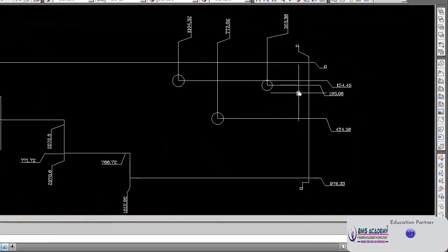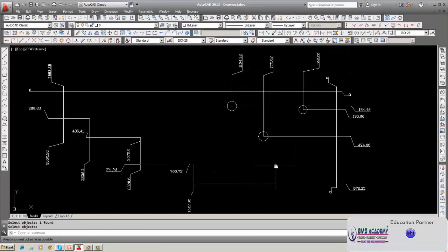See, here what we have to do is, you have a component at a place, let us assume. You want to dimension it suitable to machine on a CNC machine, taking the coordinates of these points. There are 3 holes, there are 4 edges, and all the corners should be dimensioned. For that, the component is here.